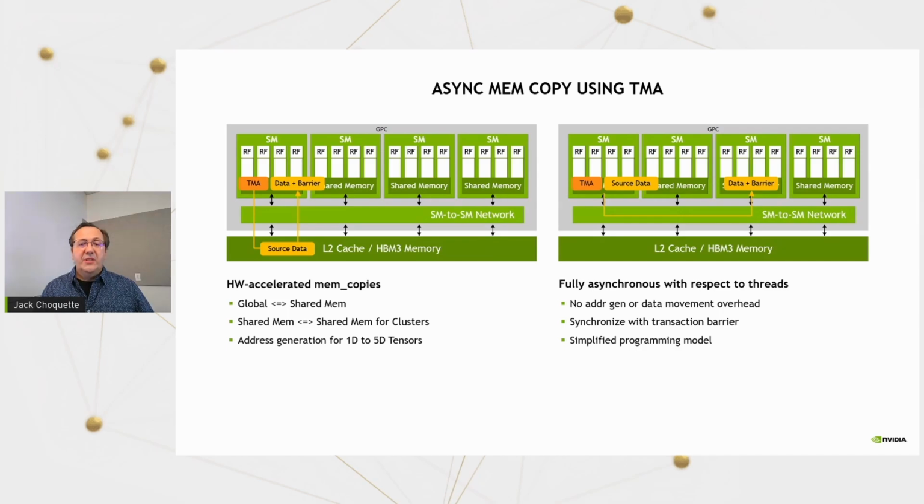The TMA is fully asynchronous with thread execution. There is no address generation or data movement and synchronization management overhead required of the thread. From the thread's perspective, it is simply fire and forget. This makes for a simplified and efficient programming model.